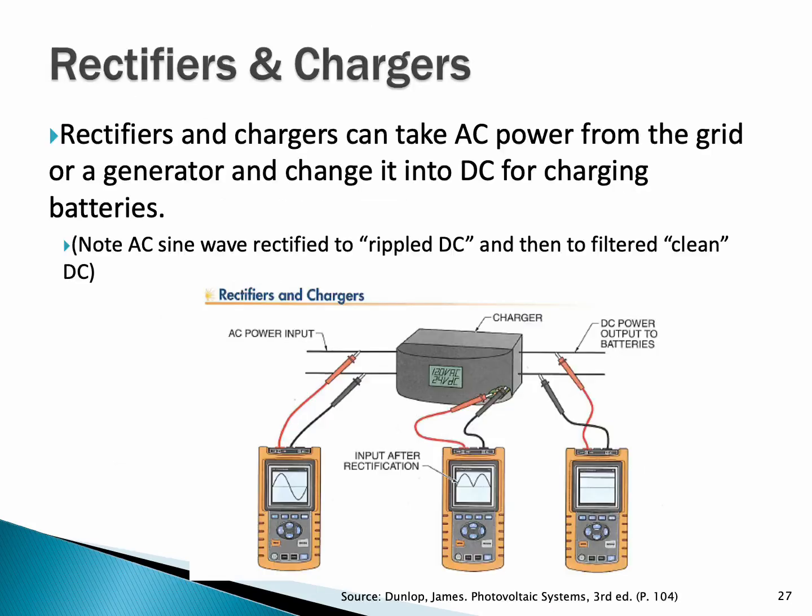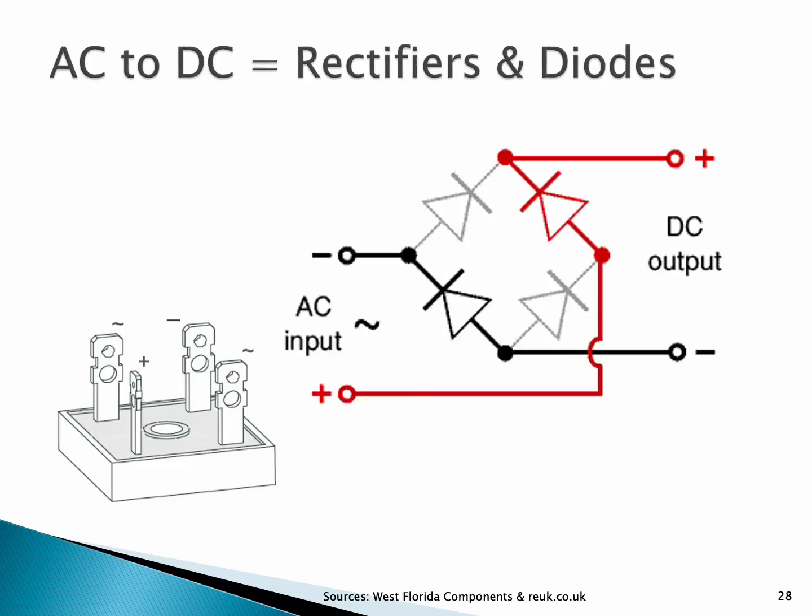When we do that, these rectifiers use diodes to cut half of the sine wave in half, and then the opposite direction flips that sine wave into the upper layer, the positive side of the zero line, so that we have a constant pulse of DC. So we're converting that AC into a DC signal, flattening it out into a constant voltage and current output. And that's with diodes.